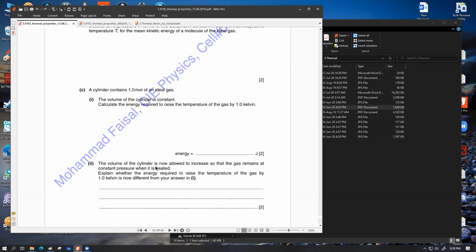What you're proposing is that if we have a small volume of the gas to start with, then the delta V of the gas can be considered negligible. That way we might say that the required heat might be exactly equal. But that's an approximation. Being the initial amount small, the delta V is considered also to be small. As a result, we can consider that all the heat that we're providing is used for temperature increase. That's possible, but that's not entirely true at a very strict level.